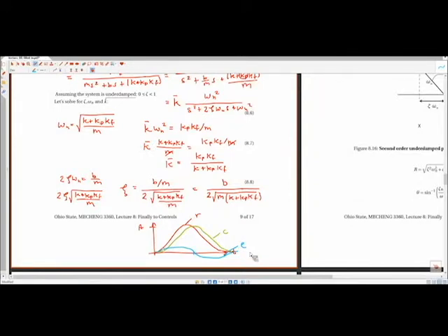Which creates a current. If you go back to your discussions of motors, torque or force is proportional to current, right? And if you look at a standard motor. And so what this is saying is, okay, so our error is positive here, right? So this means that we're going to have to give some sort of positive force because we're lagging the reference. So that's pushing the robotic system in the positive direction. And then when I reverse position, then the force is going to have to be negative, right? So this is all coming from the sign of the error.